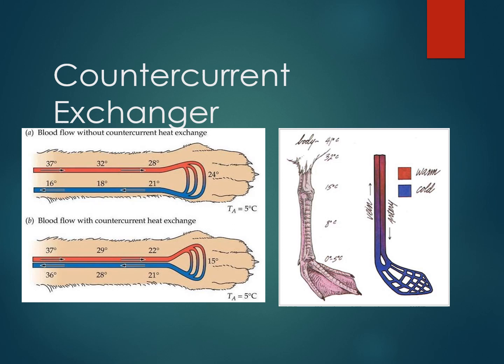We also use this in a lot of industrial processes, power plants and power generation, looking at boilers that all use this kind of technique, where we would have one hot stream of a fluid going one way and a cold stream going the opposite way. The trick is that we want to pull heat from the hot stream into a cold stream.